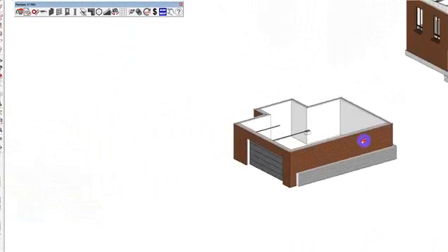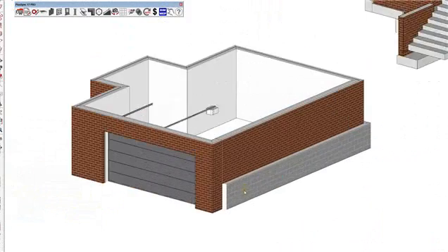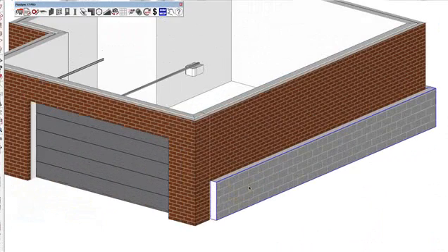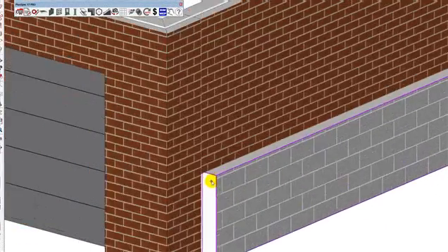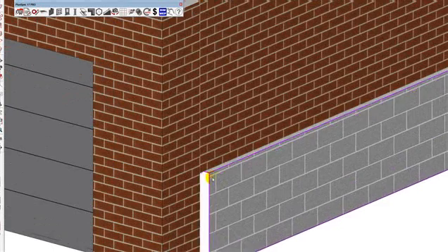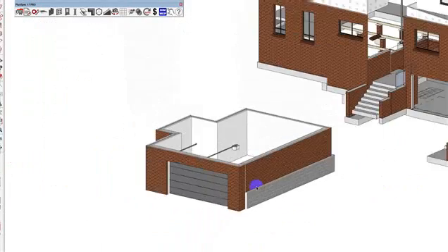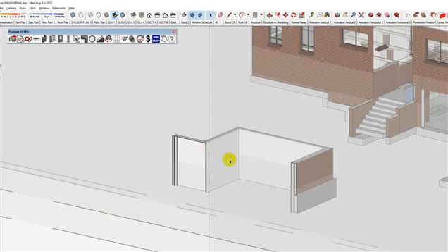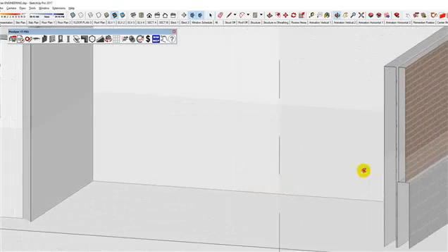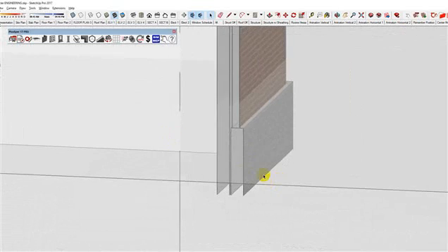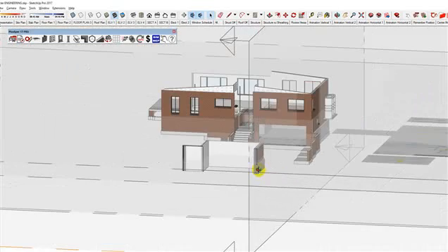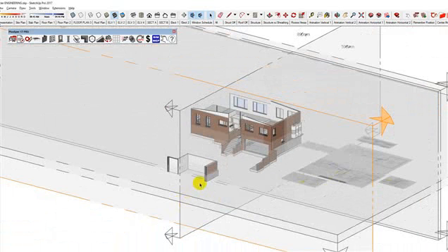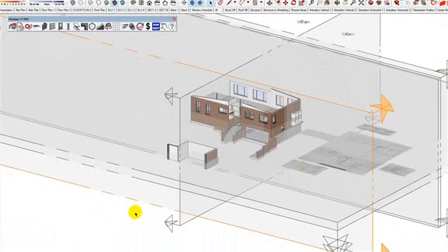Now when I did a section through that wall, obviously that one needs to push in. I've got a shortcut, shift, push, pull. You can push it in, right, however it needs to be. Right, when I run a section through here now, you'll see that it's the same as the detail. See what I mean? I'll save this model and I'll send it to you, so see if you can redo that for me. Thanks, Joey.